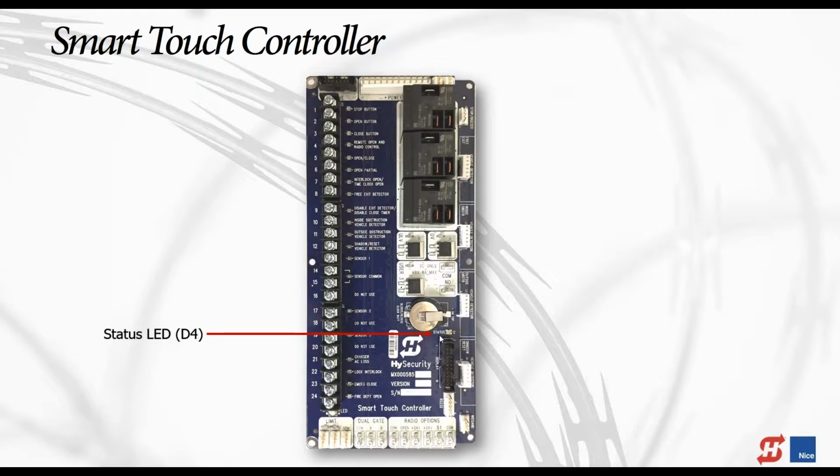All right, and the last thing here on this is a status LED. This really is a diagnostic aid. If you go up to the board and that status LED is a heartbeat, a steady pulsing on and off, right? If it's doing something different than that, let's say a long off, on, and then 2 short offs or something, it's not that regular heartbeat, call tech support. They'll help you out with that, all right?